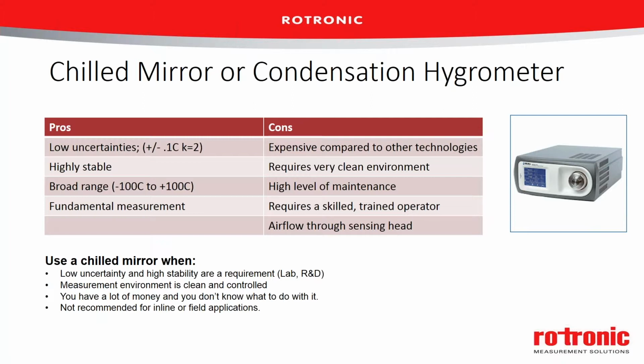There are some cons to this technology. There's a reason why you don't see everyone using them, and probably the biggest reason for that is they are definitely more expensive than the other technologies. Typically, even the lower cost chilled mirrors, they're starting at where the high-end capacitive sensors stop. So almost always you'll find a capacitive system for less than a chilled mirror system.